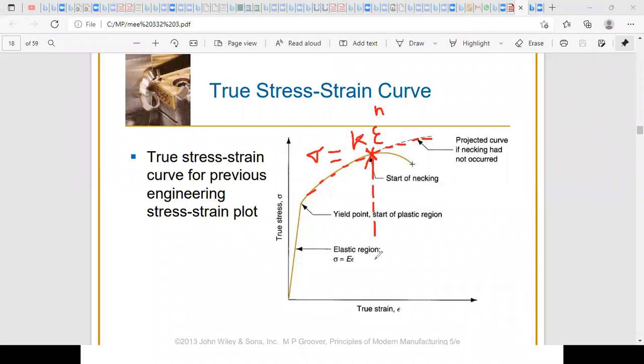Then I consider that the strain hardening zone is limited between these 2 points. So here, this is my strain hardening zone, and the remaining part is the necking part. As we said, it is not desired to reach the necking part because this will weaken my material. Now we will see together the different possible behaviors of materials and how this will affect the coefficients K and n.